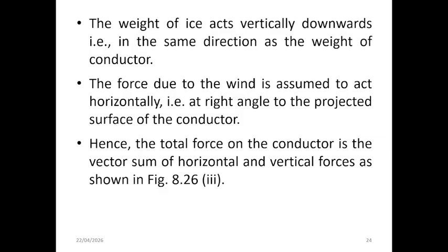We already discussed this slide as well, and then I explored real world conditions where additional forces must be considered. In particular, we examined how ice accumulation increases the vertical load acting in the same direction as the conductor's weight. At the same time, wind pressure introduces a horizontal force acting perpendicular to the conductor.